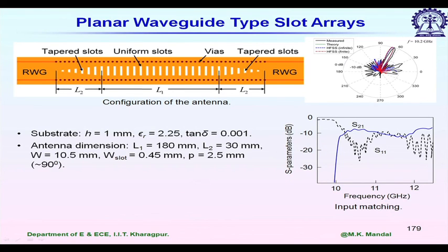So, for the leaky wave antenna, what we see is that feeding is very simple. It can be excited simply by a microstrip line or any 50 ohm line. Next day we will be discussing transitions. Not only that, we can also obtain scanning simply by frequency sweep, and for scanning purposes the preferred antenna type is the periodic leaky wave antenna, since it can scan both the backward side and the forward side. So, that is all on leaky wave antennas.